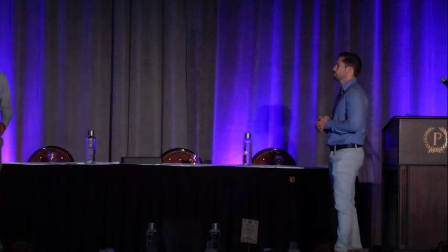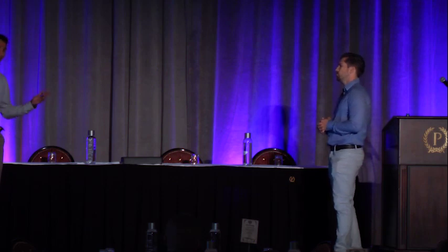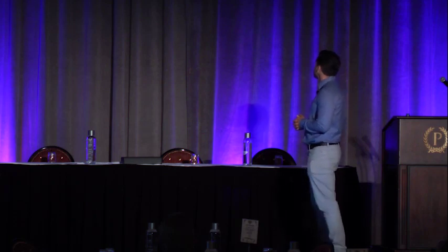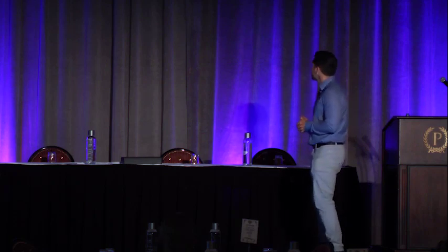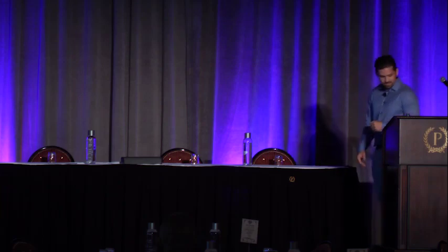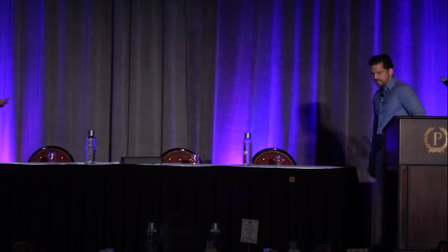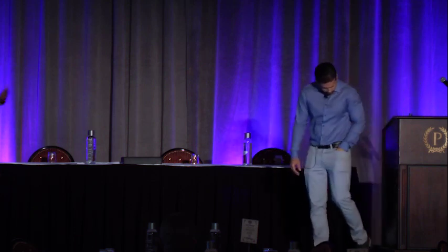This picture is a project that shows a good example of truss shoring, where a worker had accidentally backed a forklift into the column. And so what happened was the shoring contractor got a call, and he was able to come out with typical scaffolding really quickly and set up shoring to make the building structurally sound, but also leave room so they can come in after the fact and replace the damaged column.